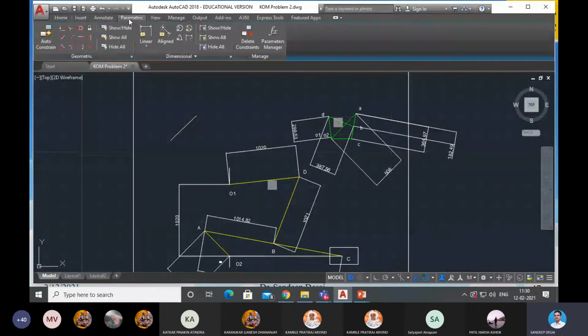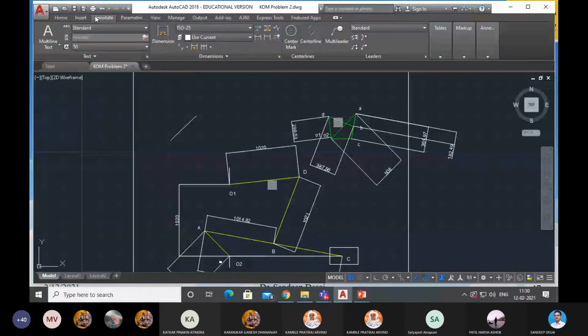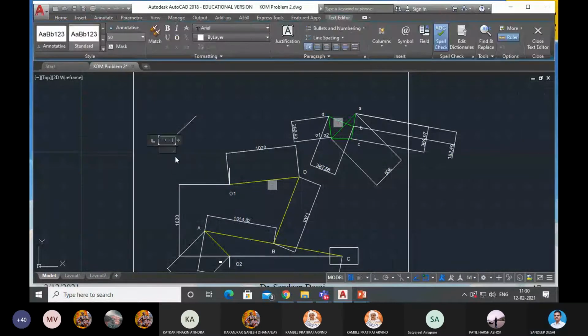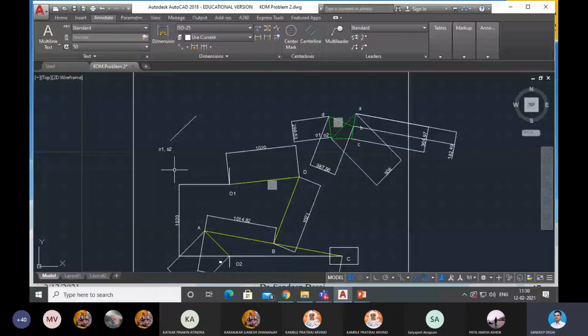So we should start here from the fixed points, and these two fixed points are O1, O2. We have discussed earlier that all fixed points should come at a common point. So there are two fixed points here. One is O2, the other is O1. All are to be represented as a common point, O1, O2, at a common location. And then from the O1, O2 point, draw a line perpendicular to O2A in the vertically upward direction, not downward, because the crank is rotating in the clockwise direction. Okay, vertically upward direction. But now it is not perpendicular to O2A.